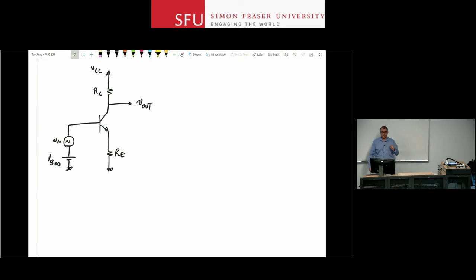We're going to talk about the biasing very soon, in the next lecture. But this resistor in the emitter circuit will absorb those changes of VBE, and will control the behavior of the circuit by a great deal. So for example, if you want to go back to the diode section and diode discussion,